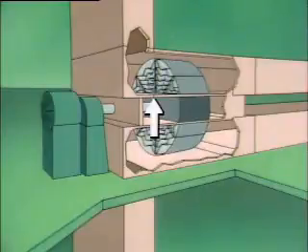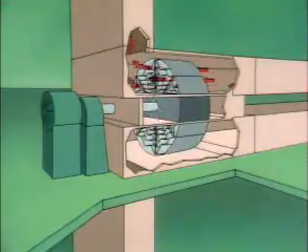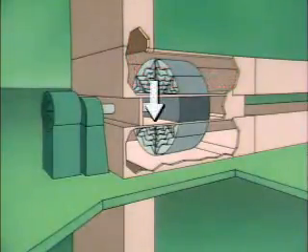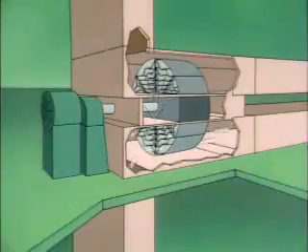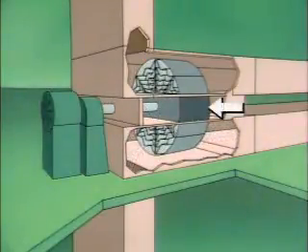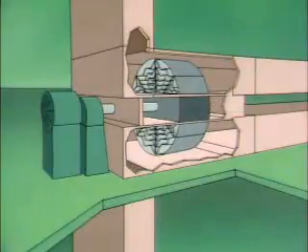The top half of this heater is in ductwork that routes hot combustion gases from the boiler through the air heater and on to the stack. The bottom half is in ductwork that directs incoming air through the heater and on to the boiler. A seal prevents hot combustion gases from mixing with the air flowing to the boiler.